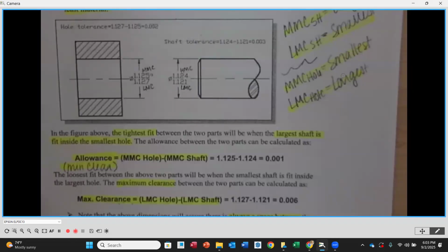So if I was going to make that hole, what's the size drill? I don't know. Hopefully there's a 1 1/8. It's a drill bit size, right? So when you make that part, and say over time I make 120 of these, and that drill starts to get dull, what happens to the hole size? It's smaller. It does not. When you have a dull drill, it actually increases the size of the hole. It's always kind of the opposite of what we think.